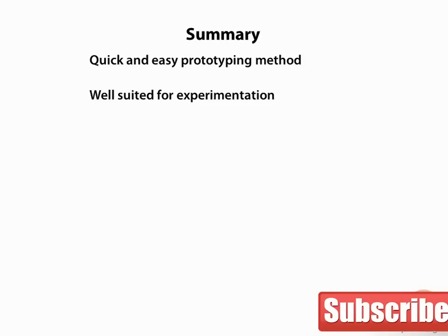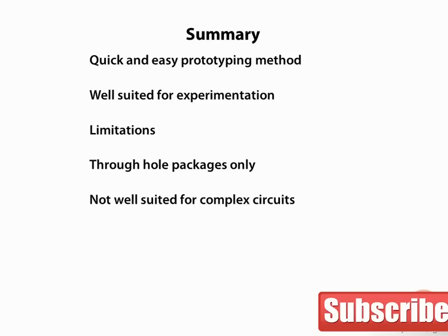Breadboards are extremely useful for prototyping temporary circuits and trying out different ideas. We'll be using this method primarily for this course to build our different demo circuits because it's easy and quick. Breadboards do, however, have their limitations. Very complicated circuits can get quite messy, and the jumpers can get knocked off if not careful. There is some contact resistance on the spring contacts, and this can make a difference in some circuits.